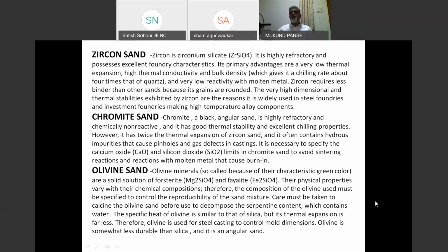However, with zircon sand full molds, it is difficult to make castings, as the metal gets chilled and you get a lot of cold shuts. Zircon sand is used only for chilling purposes, so that sand doesn't fuse in heavy sections of a steel casting. The advantage of zircon sand is you can mix it with silica sand, 50% zircon, 50% silica, something like that, to get the effect of both the sands. You can reduce the consumption and you can have some effect of neutral chemical reaction. But again, this use is restricted to heavier junctions only.